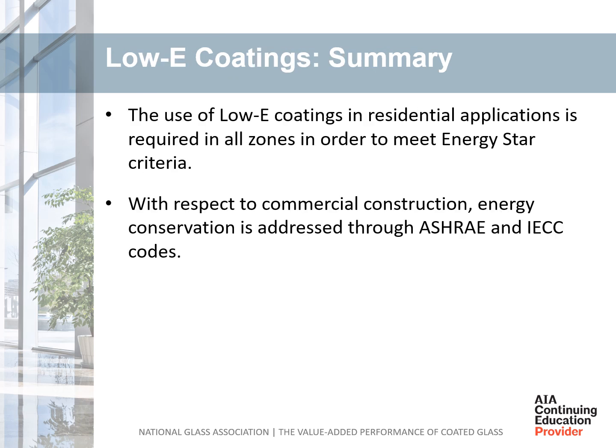In summary, low-E coatings are now required across all climate zones to either help meet low solar heat gain coefficient requirements in the south or the low U-factor requirements in the north. Low-E coatings are necessary to economically produce glazing products which meet code requirements that become ever more stringent. The commercial market continues to utilize an ever-expanding line of low-E products which provide an ever-increasing level of performance necessary to meet the demanding ASHRAE and IECC codes.